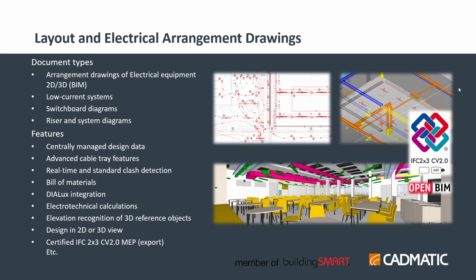All these can be imported from DIALux. In electrical, we also have electrotechnical calculations available. For example, you can calculate one-phase or three-phase voltage drop, short circuit current, powers, output power per group, per load, per cabinet.